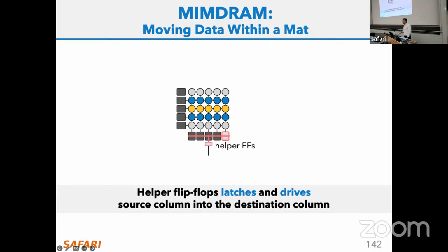DIMMs have buffers as well for signal integrity, both for data and for command and address. Those are buffers placed in the DIMM itself. So you have your DRAM DIMM, and in the PCB of the DIMM you place some extra buffers so that before we move the data, the column address is amplified. That again improves signal integrity. So hopefully it is outside the DRAM chip basically.